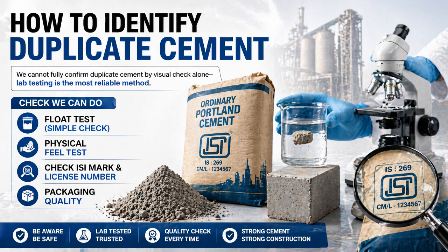Now everyone's mind has one question: how to identify duplicate cement? One thing I would like to tell is that we cannot fully confirm duplicate cement by visual check alone. Lab testing is the most reliable method. However, by some simple tests we can identify whether it is duplicate or not. Since visual checks alone cannot fully confirm it, we need to carry out some simple tests.